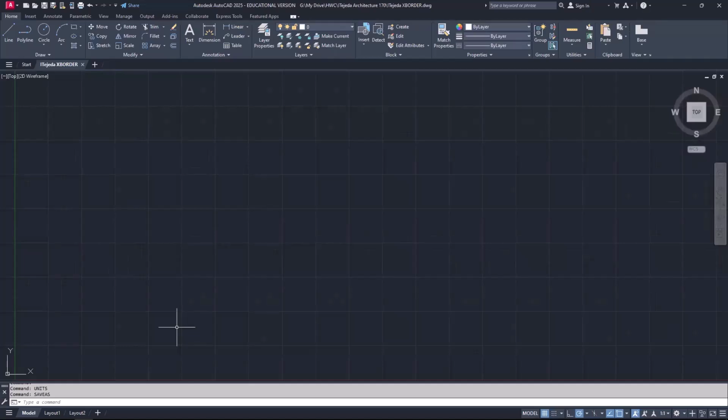All right, so this is going to be the border. Oh yeah, let me turn off the grid. That's just personal preference. And what we're going to do is we're going to be printing out PDF files of the floor plan, site plan, elevations, and we're going to print them out on 11 by 17 sheet sizes, which means that if I'm going to use that sheet size, then I want to generate a presentation border that is just a little bit smaller than that. So here's how I recommend you do this. And by the way, we're just on layer 0 right now. I'll take care of layers later. I'm going to zoom out a little bit here.